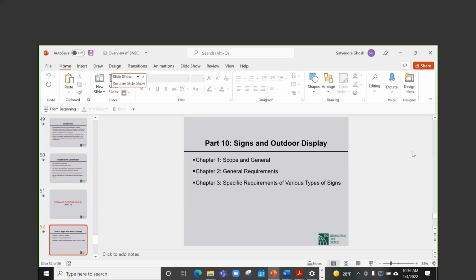And the way we do it has changed in ASCE 7. It used to be based on tributary area. Now it is dependent on influence area, but that goes into details that may be unnecessary at this time. So the basic idea is what is important, and live load reduction is about the fact that on a large area, the entire area will not be fully loaded with the design live loads.